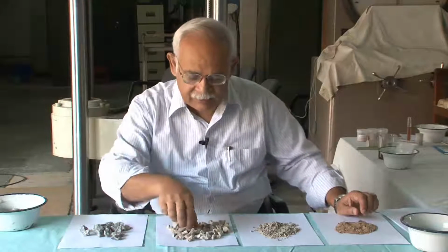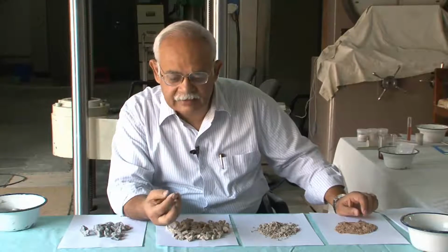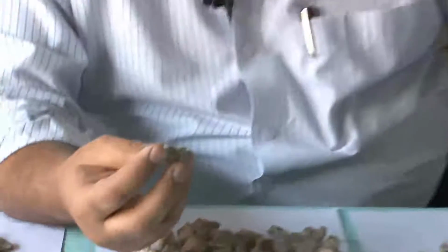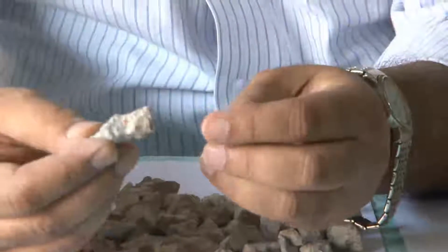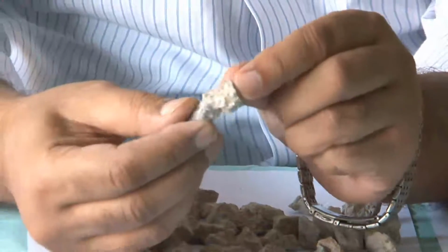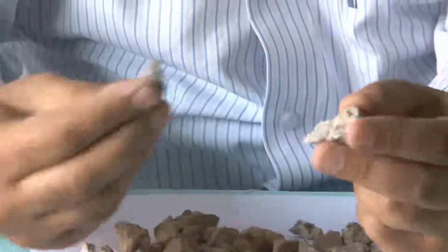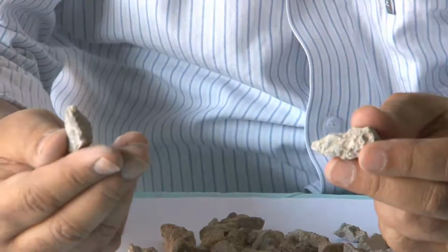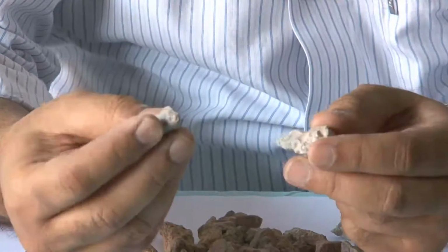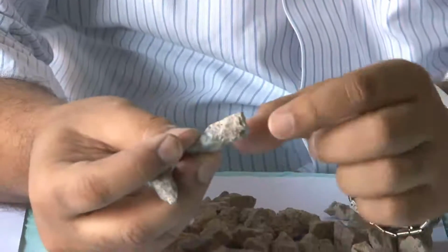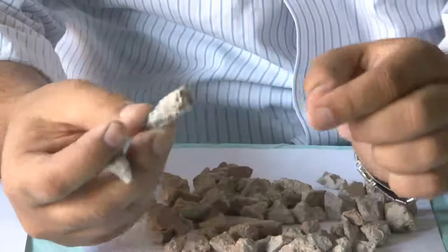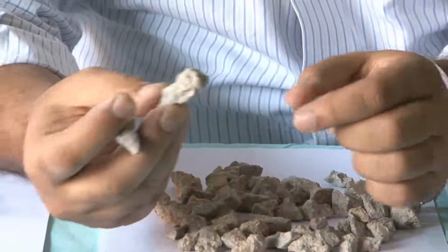Notice that recycled aggregate is different from naturally occurring aggregates. Recycled aggregate often has mortar sticking to the surface of old aggregates. So, sometimes we have old aggregates which also have a coating of cement paste or mortar, and sometimes particles of mortar or portions of mortar adhere to the coarse aggregates.